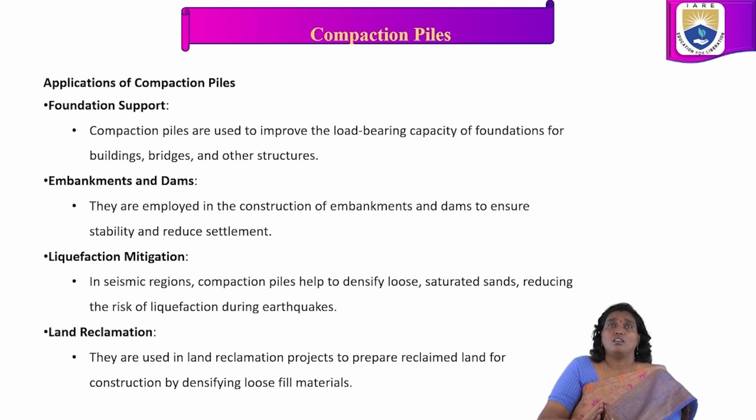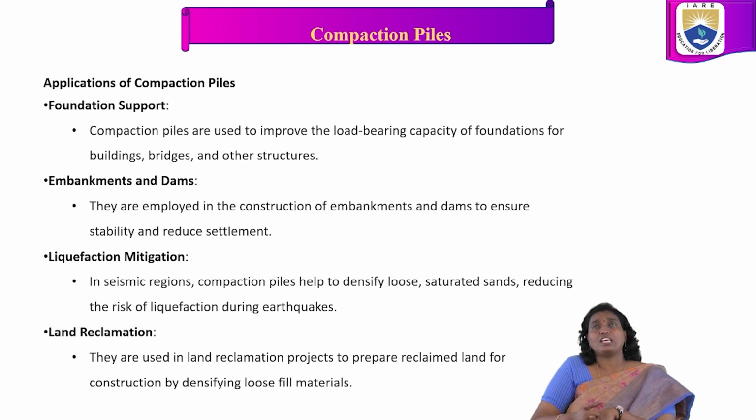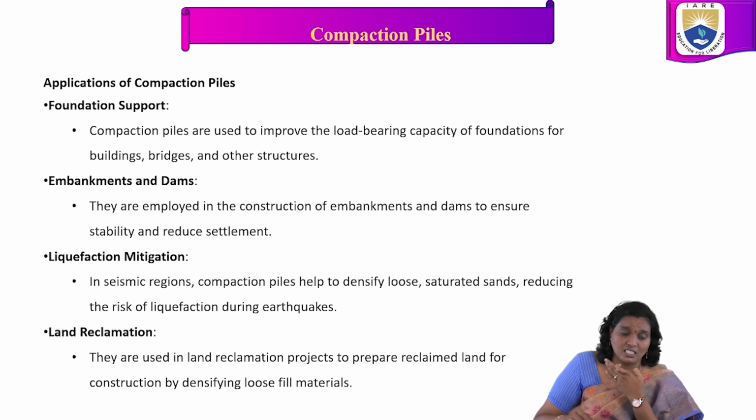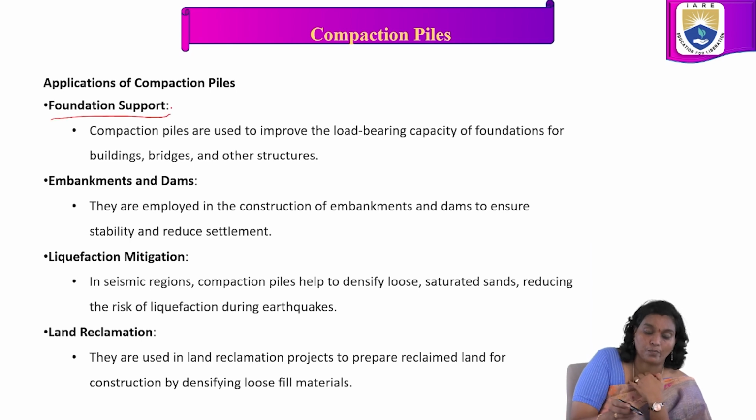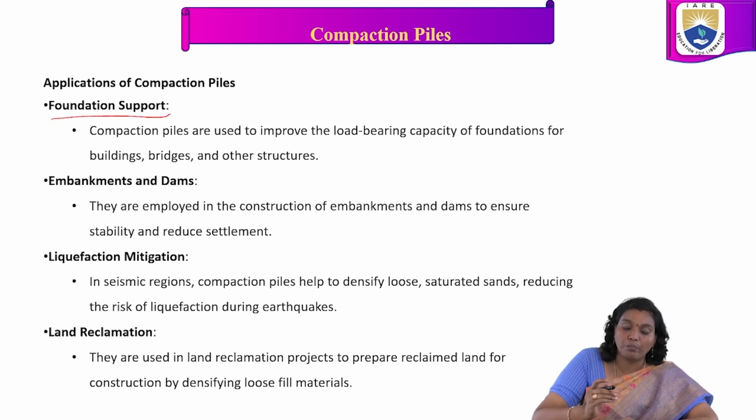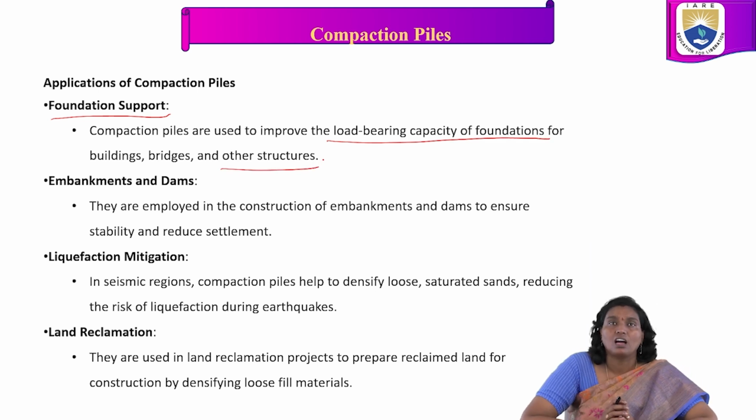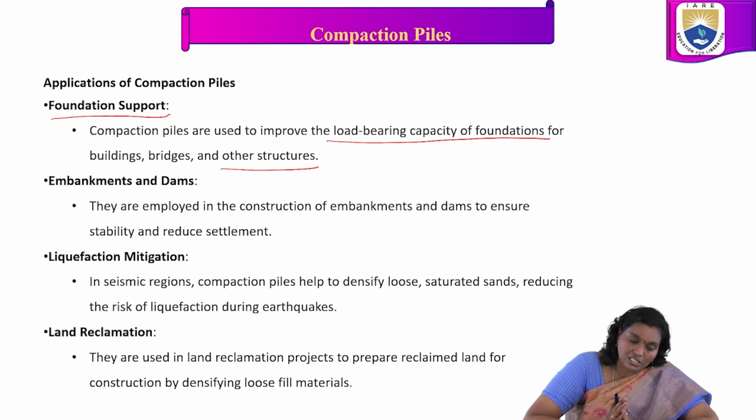Coming to the applications, where we are going to apply compaction piles. The first is foundation support, and the next ones are abutments and dams, liquefaction mitigation, and land reclamation. These are some of the applications of compaction piles. In this, the first one is foundation support. Compaction piles are used to improve the load bearing capacity of the foundation for buildings, bridges and other structures, and also to prevent foundation settlements. Such foundation settlements do not happen because of using these compaction piles.